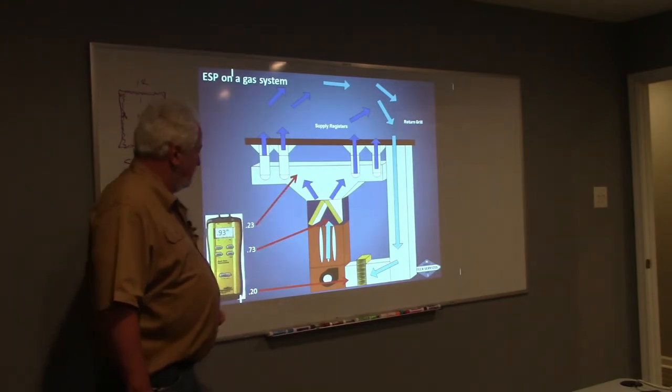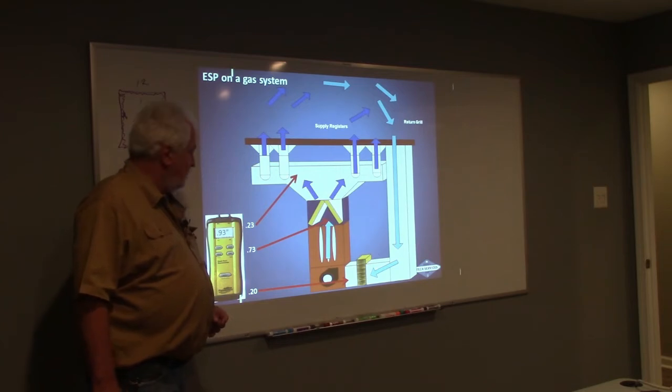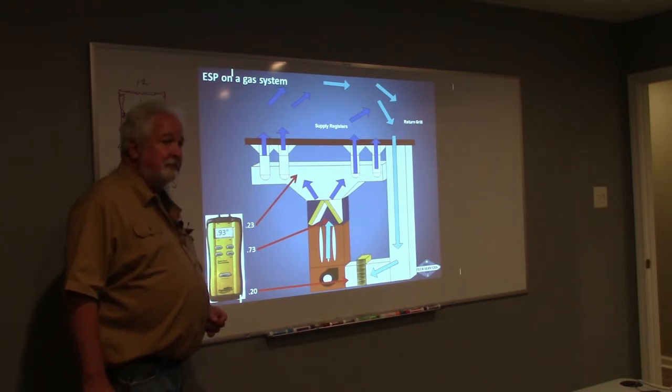Way too close. 0.5? Remember those readings on those coils? Even the highest restricted one that I showed you was like a 0.3, wasn't it? Right now you've got 0.5 on this coil. What do you think's going on with this coil? Coil's dirty. Yeah, coil's dirty.